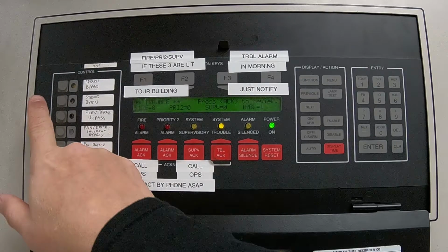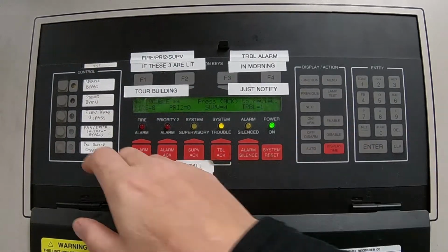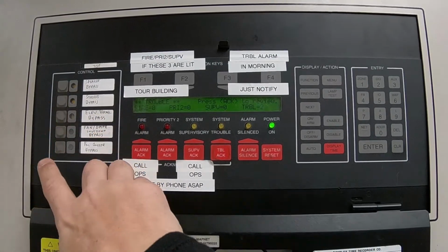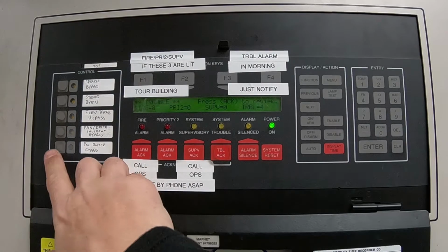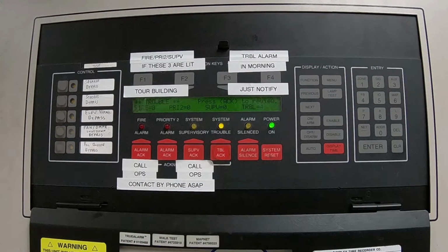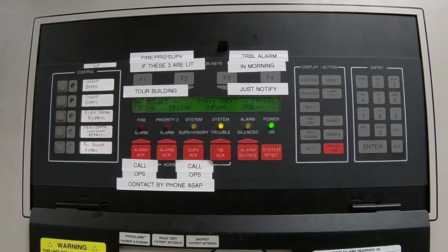We just bypass them, so now you'll have no sound like fire alarms going through the building. Strobes, which are the flashing lights, elevator recalls, fans and dampers, and this one here is the panel buzzer, which is the buzzing you just heard. Once they are in bypass, you can work on any of the system's issues and you won't have any of these alarms go off, which means you won't be recalling elevators, and no lights and sirens will be going off.